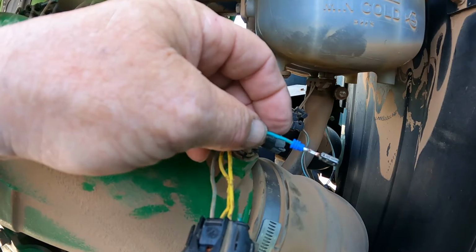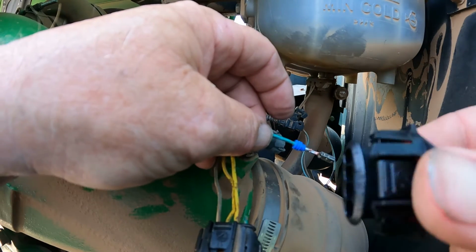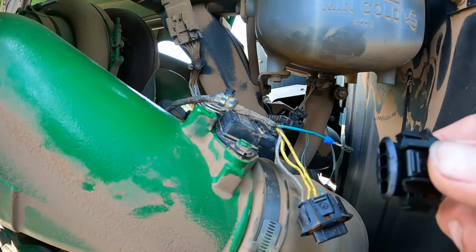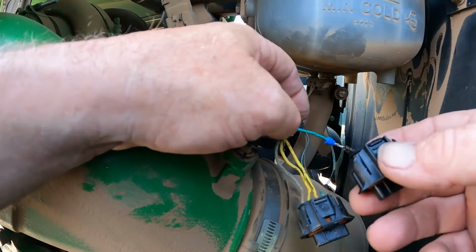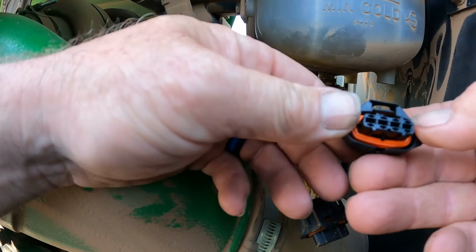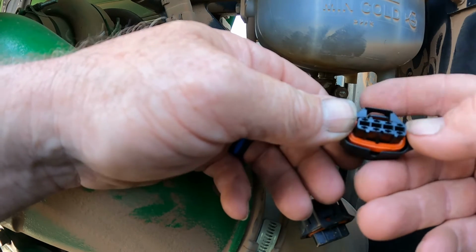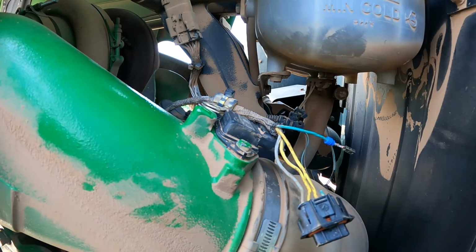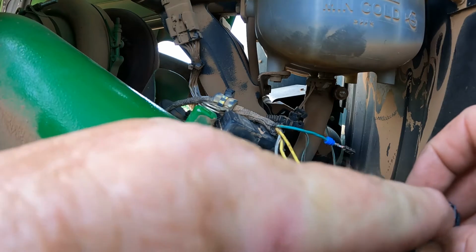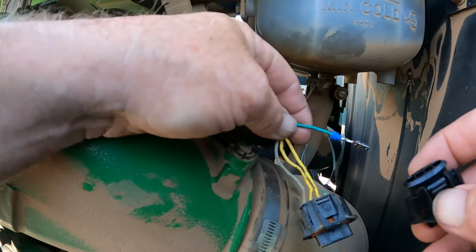And so I'm going to go ahead and show you how to install that in the new connector housing, and then we'll go ahead and carry on and fix the other 3 wires, okay? Now keep in mind that your connector housing has a locking device here that locks on the sensor, so that would be a pretty good indicator on which cavity to install this green wire in, okay?